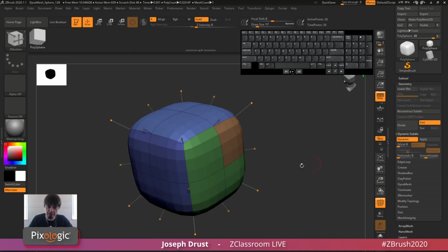And if you turn this on, it's going to preview what that model is going to look like smooth. And so down here you have a smooth subdivision level slider here, and you can actually turn this up or down, and this is going to allow you to preview that model with more subdivisions. Now this model isn't this tessellated, it's just a preview. So if you hover over it, you can see that it's basically working on like this cage or the low res version of it basically.